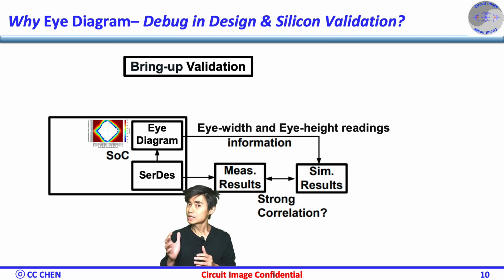According to our experience, the correlation between the measurement and simulation results is not aligned well because of the local OCV. If we can get the precise PVT information locally in the measurement, we can apply the same and precise PVT conditions into our simulation. Then, the strong correlation will not only help our design confidence, but also catch some discrepancies due to oversight bugs.